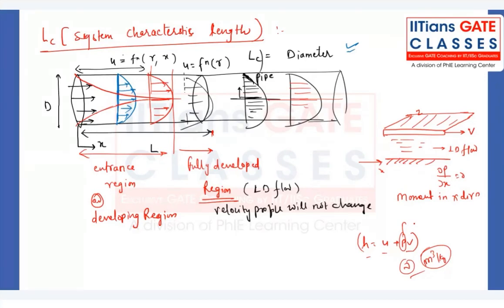No, that is a different thing. That we say in terms of point function: at a particular point, we can define that property, right? But work and heat depend on the path, they are path functions, not point functions. If you change the path, work will change. Adiabatic work is different, constant volume work is different. So at a particular point, you can't say work.